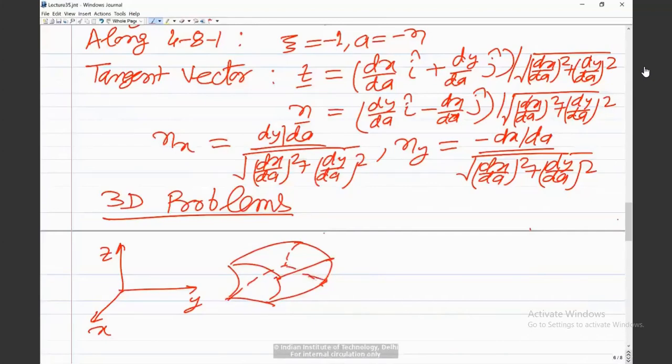Now if you look at the nodes, first I'm numbering these corner nodes. Let us say this is 1 2 3 4, then mid side nodes, so this is 5 6 7 and 8, then the nodes at the top, so let us say this is 9 10 11 12, and then mid side nodes, so 13 14 15 and 16, and then these nodes, so this is 17, this would be 18, this would be 19, and this would be 20. So this is the 20 noded brick element in the physical coordinate space.